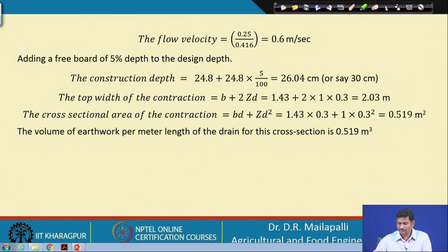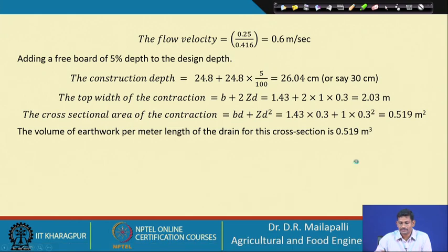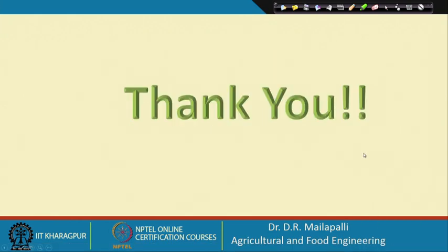So, this way you can estimate the geometric parameters of the trapezoidal cross section or ditch. Okay, so in this the main design, from hydrologic design you will be knowing the Q value. So in hydraulic design, knowing the Q value, you have to assume, so mostly the trapezoidal channels will be used for designing the drainage ditches.